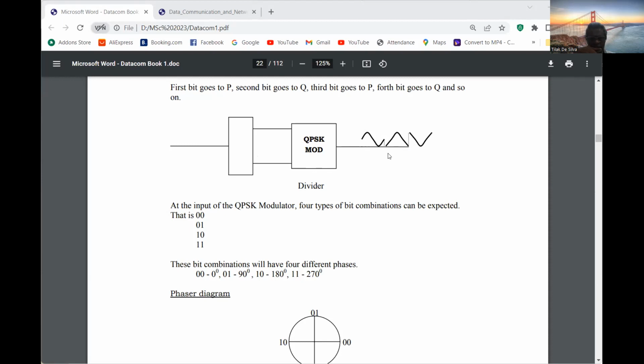Yeah. So basically, when we are using AM or FM, we can put it to air with the antenna. In radio broadcasting, we use AM or FM. So in which instance are we using this PSK method? That's what I'm asking. If it is a digital signal, AM, FM is for the analog signal. Okay. So if it is a digital signal, first you convert it to an analog signal by using this ASK or FSK or PSK.